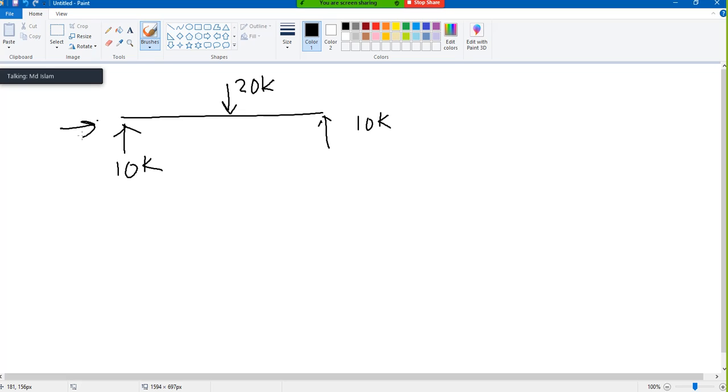Shear force and moment are very common and very important. In fact, the design of most civil engineering structures is just shear force and moment. 90% of your civil engineering life is shear force and moment. So step number 2, to draw shear force, what to do? Follow the loads. I'm writing this very small sentence, but it is very important.